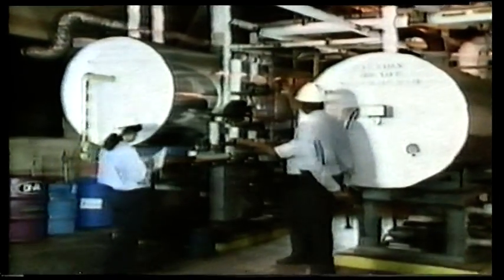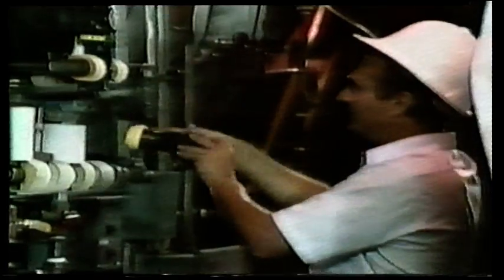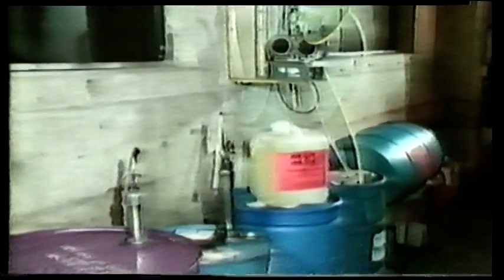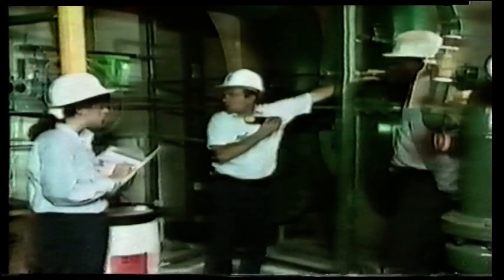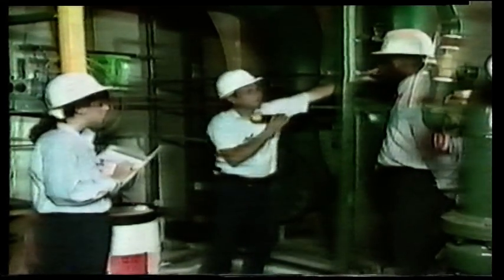The survey next addresses the water feed to the boilers. The hospital's plumbing system has a separate line for all processed water, which includes the boiler supply. Through the interview and inspection process, the survey team determined that the boiler water contains toxic chemical additives, specifically descalants and deoxidizers. Further discussion and inspection by the survey team revealed that the same processed water line supplying the boilers also feeds the air conditioning cooling tower, and that chemical additives are utilized.